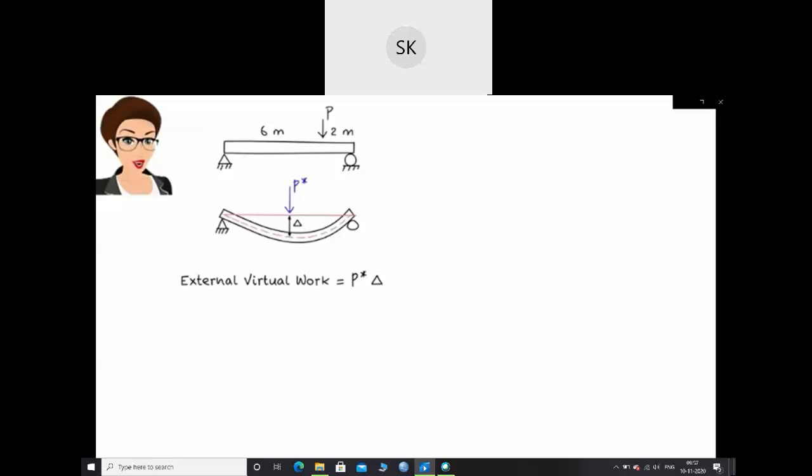Bending moment. When dealing with beams, we generally consider bending moment to be the only internal force that contributes to the structure's deflection. But since bending moment is not constant throughout the beam, we need to express it using an equation. Here, the virtual load is placed at the midpoint of the beam. Therefore, the beam's virtual internal bending moment can be written as.